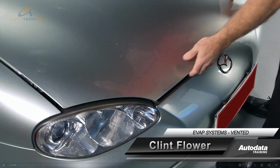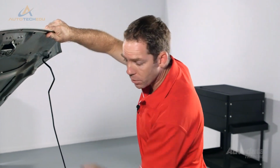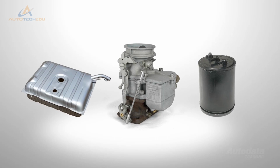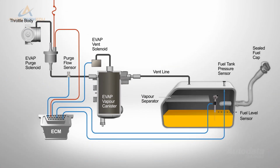Evap systems have been fitted to vehicles since 1970. Their purpose is to collect fuel vapours from the fuel tank, and in earlier vehicles the carburetor float bowl, store them, and at the correct time move them to the intake manifold for combustion. Evap systems have changed over the years from simple float bowl and fuel tank vacuum operated types to fully sealed OBD2 monitored and ECM controlled systems.